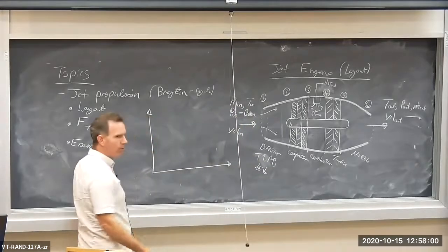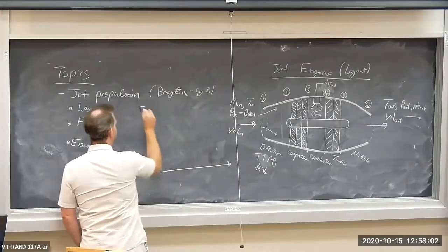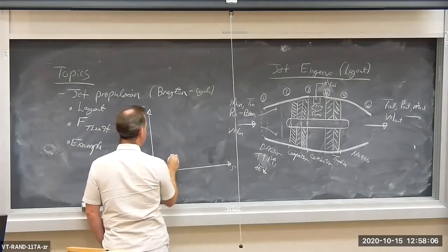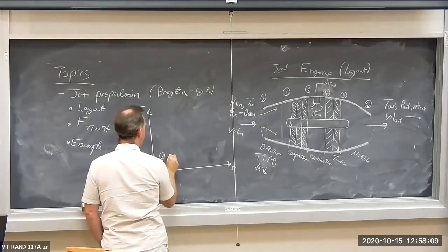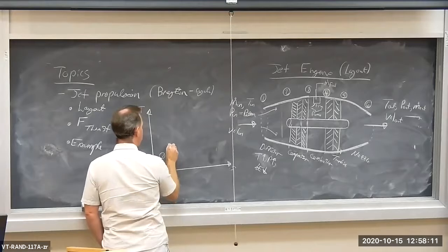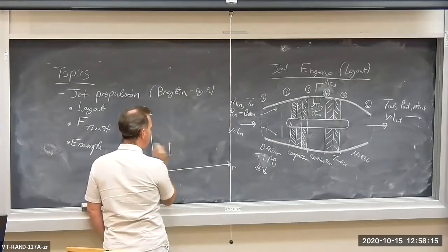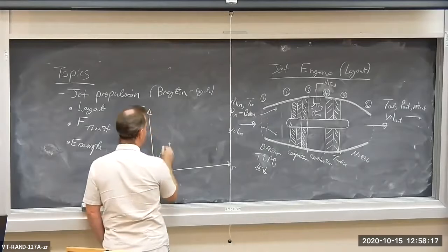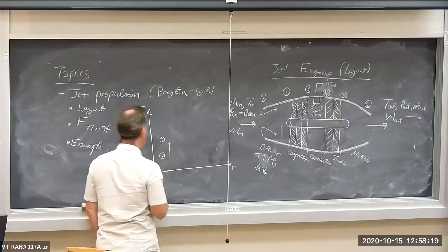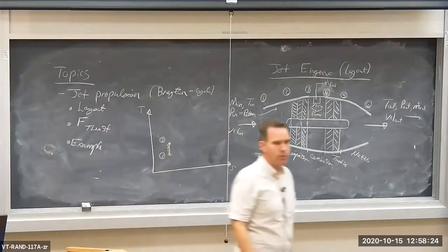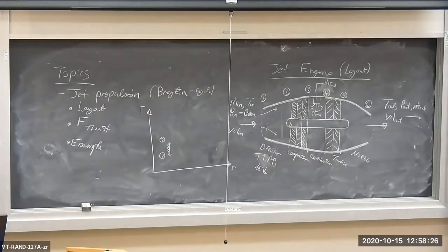Now, if this is a reversible diffuser, so we have temperature and specific entropy. Starting off at state 1, going through the diffuser, temperature goes up, and if it's reversible and adiabatic, entropy is constant, so it's isentropic. So going through the diffuser, we have a temperature and a pressure rise from state 1 to state 2.